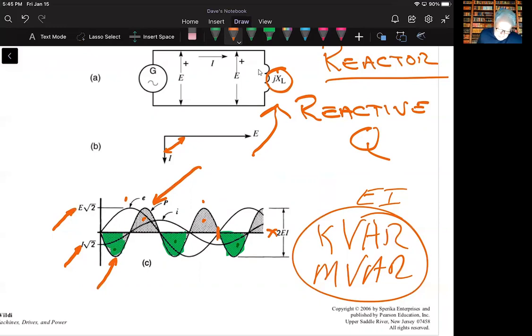So when the power is positive, the field is building up inside the coil. A moment later, when the power is negative, the energy is delivered back to the source. We have an explanation for the brief negative power pulses in figure 7.1. In effect, they represent magnetic energy previously stored in the motor windings that is returned to the source.